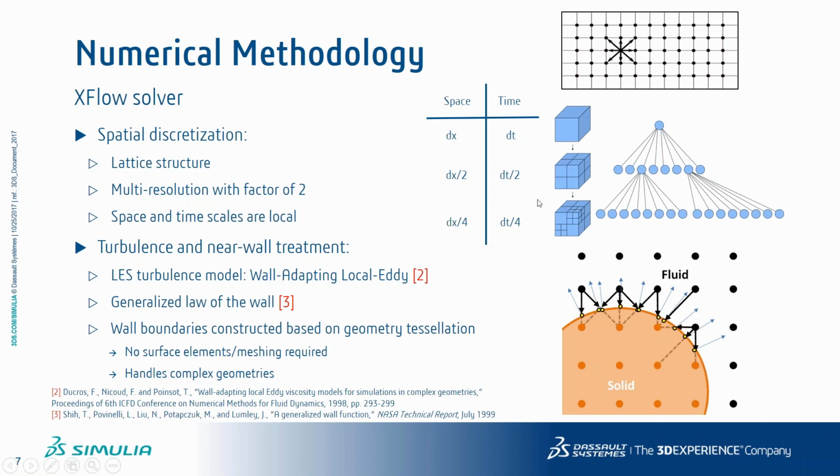In fact, you don't have to use a uniform lattice spacing across your entire domain. You can actually use different resolutions at different locations. For example, if I want to refine near my cylinder, I could have some finer, smaller cubes in some regions and others. Basically, you can take one of the voxels that represents a small fraction of fluid around the lattice node, and you can split that voxel into 8 voxels, and then again split it into 8 voxels again.